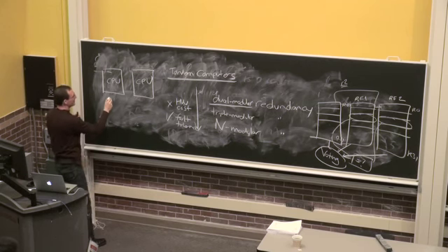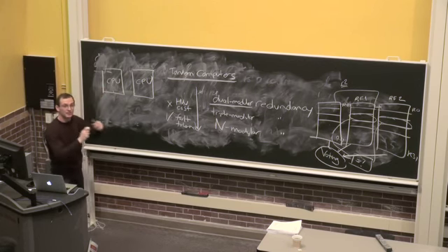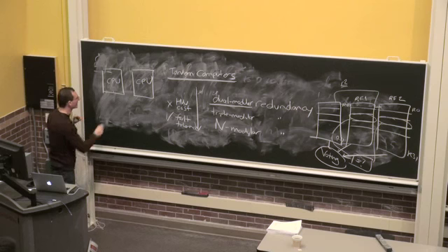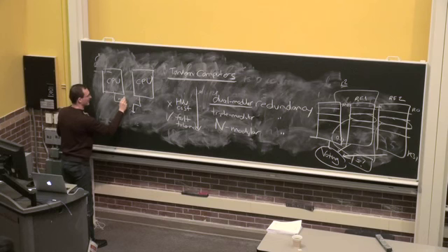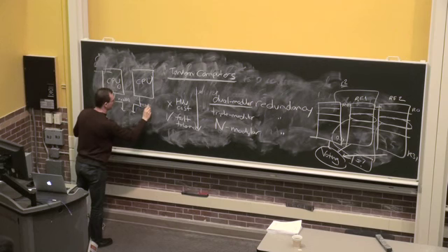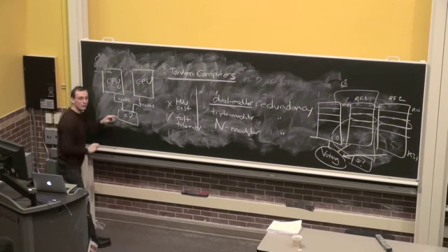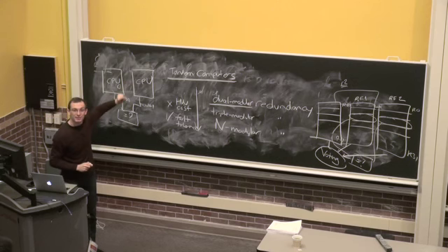The idea is, basically, when you execute an instruction, before you make the results of the instruction visible to the architectural state, before you write to the register file or memory, you check result from CPU 0, result from CPU 1, and only if they're equal, then you write the result to the register file or memory, make it visible to the architectural state.